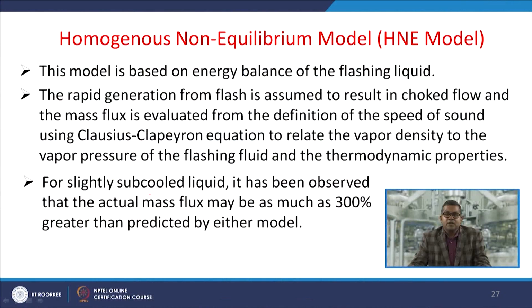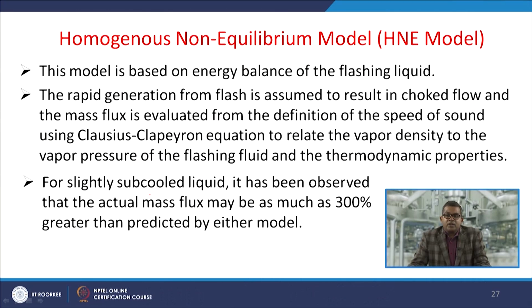Another model is the homogeneous non-equilibrium model, that is the HNE model. Now, this particular model is based on the energy balance of the flashing liquid. We have encountered and discussed the flashing concept in the previous slides. Now, the rapid vapor generation from flash is assumed to result in choke flow, and the mass flux is evaluated from the definition of the speed of sound, using the Clausius-Clapeyron equation to relate the vapor density to the vapor pressure of the flashing fluid and the thermodynamic properties. So, whatever thermodynamic properties are required, we can use this particular model.